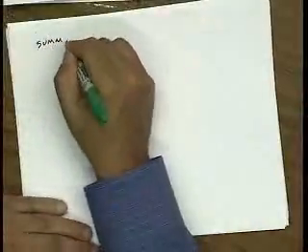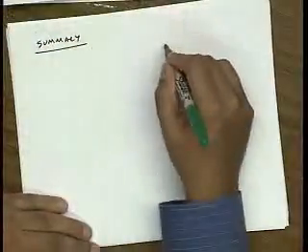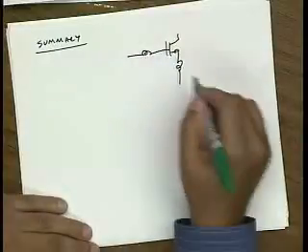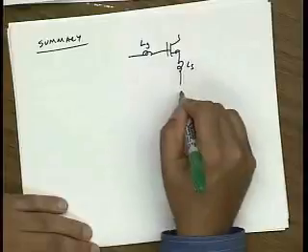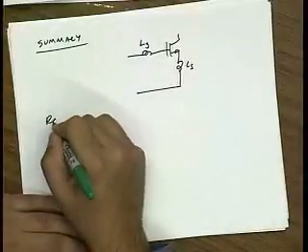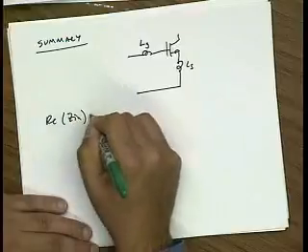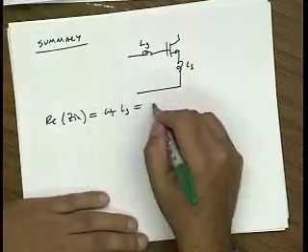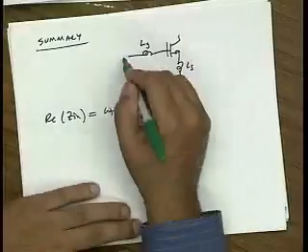All right. So let me summarize what we have so far. If I take a transistor, inductively degenerate it, and add a gate resistance, then I can make the real part of Zin equal to omega t Ls, and I can set that equal to Rs.